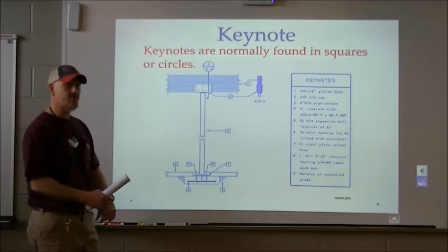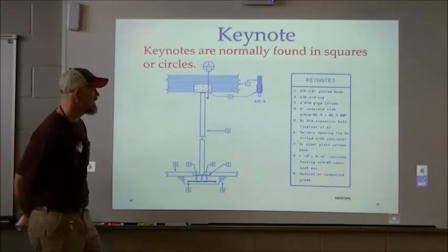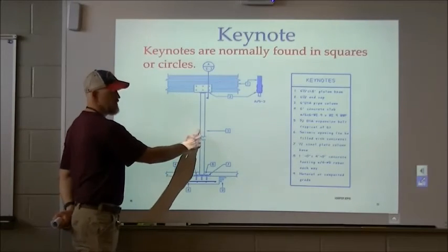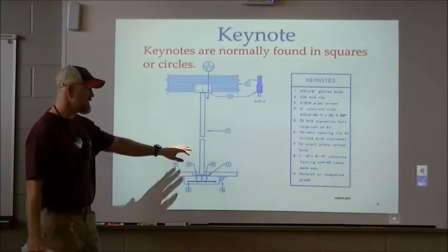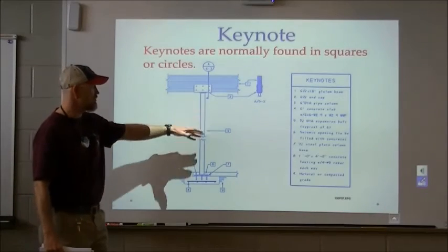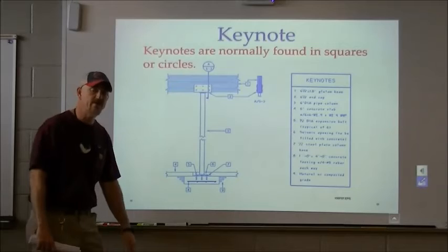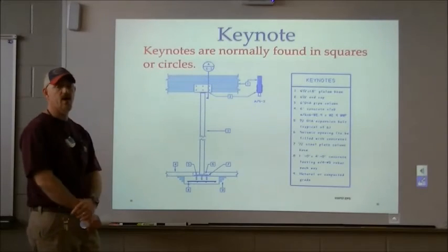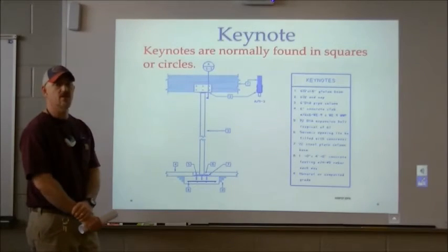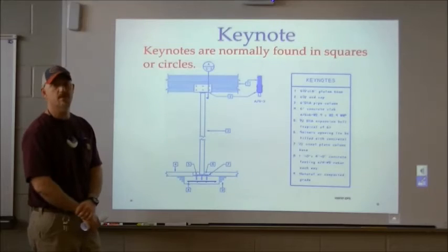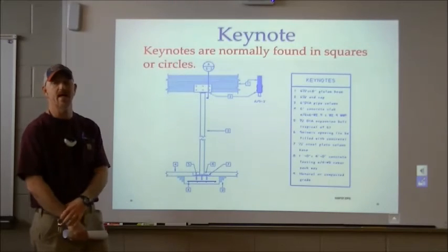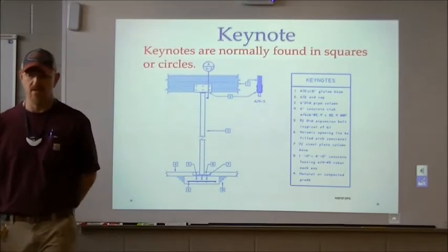The other thing I'd like to point out to you on this drawing is this break line right here. And what they've done there is they're just saving space. This pipe could be 20 feet tall, and there's no need to show that whole 20 feet because it would just be 2 lines running up the paper and it'd be a waste. So they use a break line and they don't have to show the entire thing.